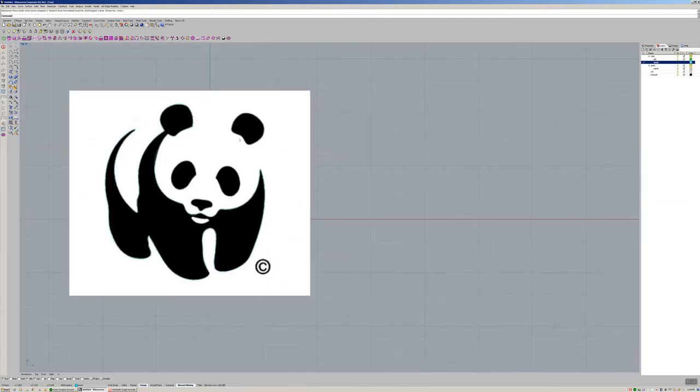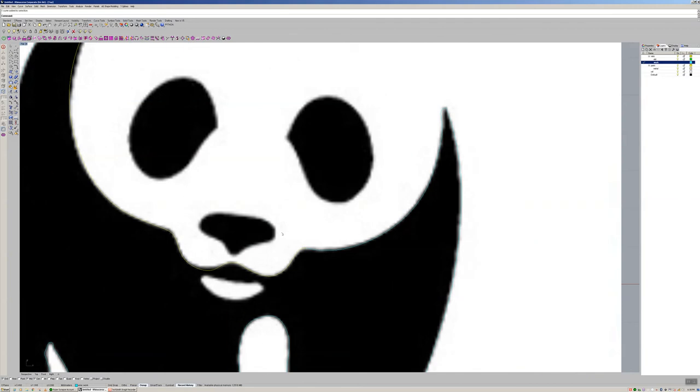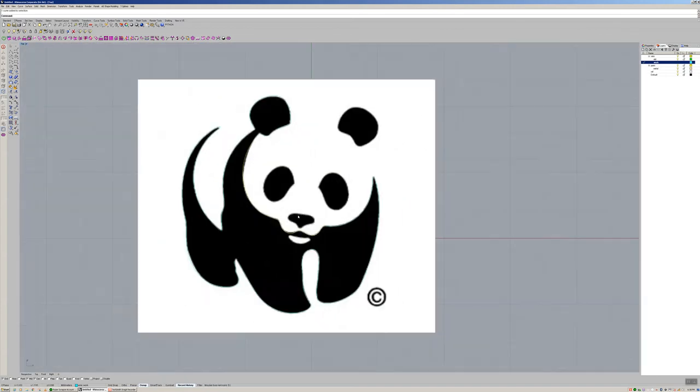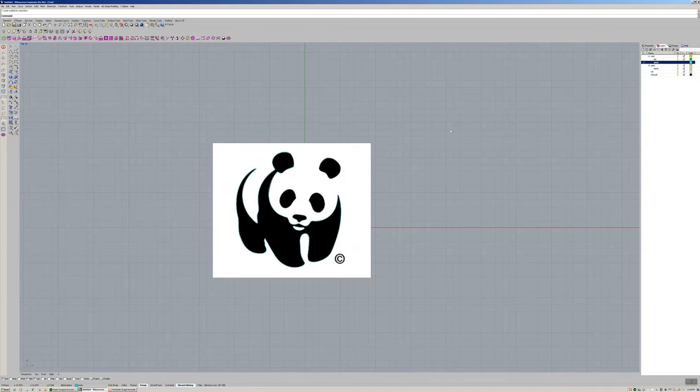Like that. So now when I select it, they're all going to be separated. You see the yellow part is showing up and the blue is not. What does that mean? It means it's not joined. So the next command I want you to learn is the join command. I'm going to left click, drag, and select all the curves, like a box around it. And we're going to hit the join command, which is right here. It looks like two puzzle pieces put together.